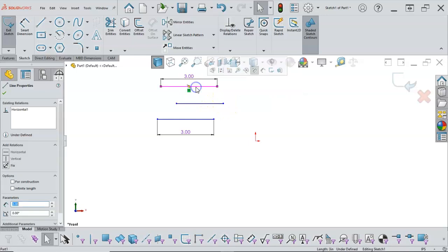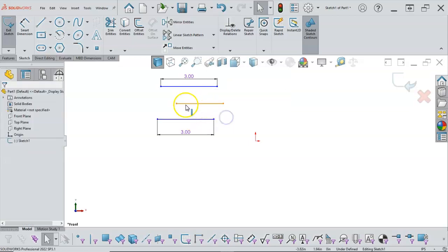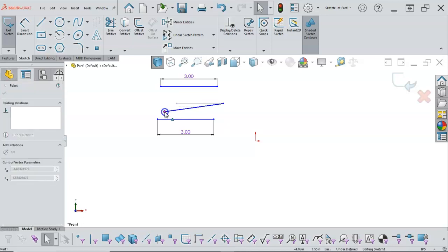So let's look at the relation. That one got a horizontal. That one also inferred a horizontal, and if we go back and look at the video, we would probably see the little yellow box popped up, and I didn't think to point it out. So making an endpoint coincident, I'm just left click, hold down, and drag. And again, this is showing up in magenta because of my first selection color. Yours may be a different color.